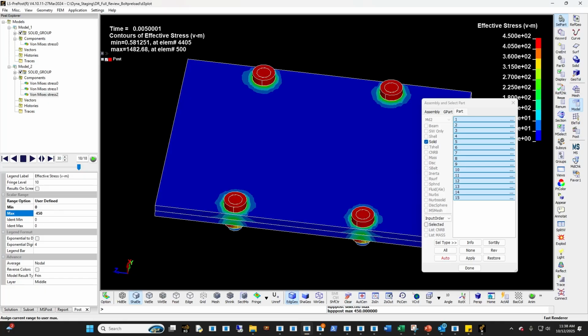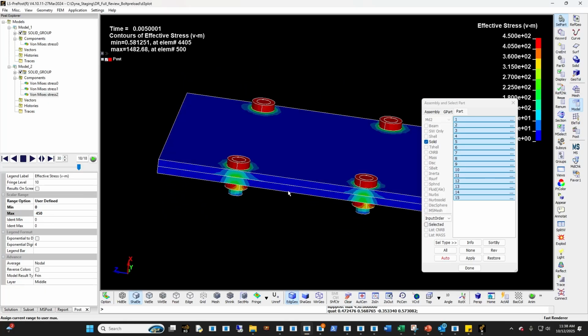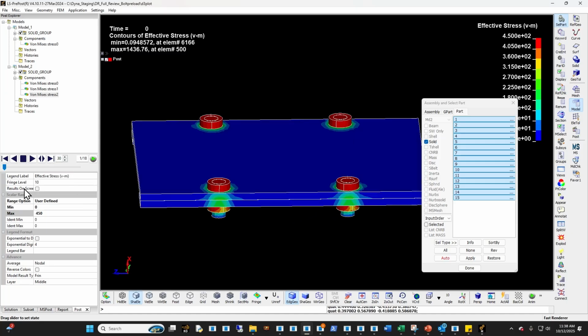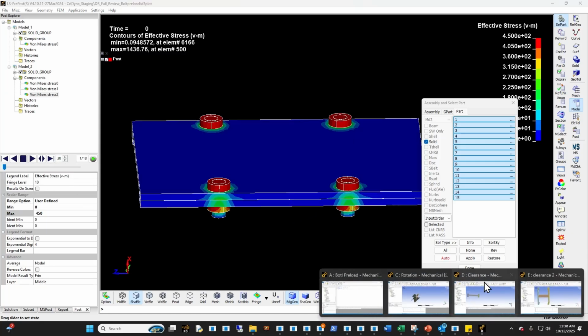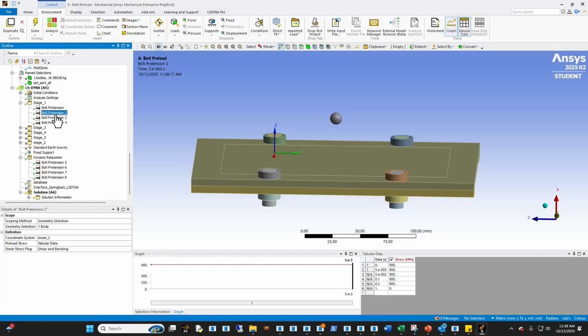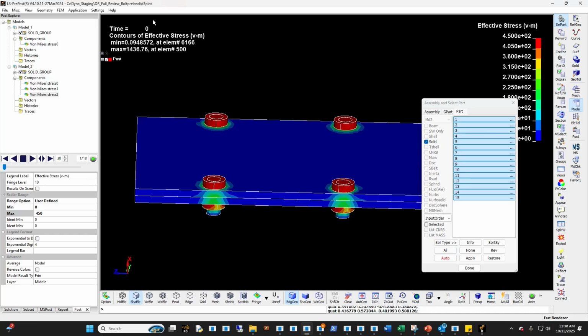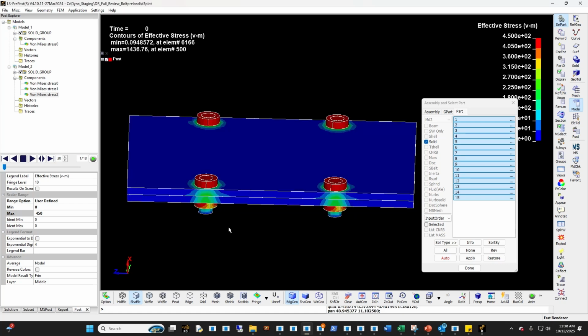Set to 450, you get both preloads applied to the analysis, and you can see the beginning and the end is the same because I'm applying a 900 megapascal stress across the whole thing without any ramping. This is how you know at the very beginning at t equal to 0, this is the pre-stress that you're looking at. Okay, and that's in essence what it is.